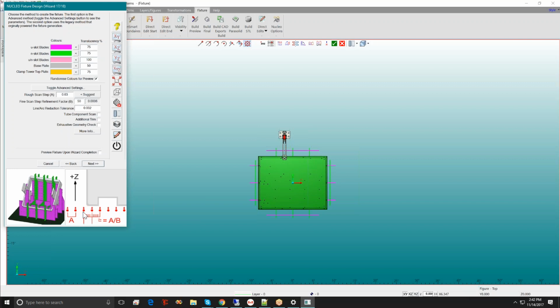And then it goes round, and in the corners, when it thinks it's detected a corner, it goes and looks in that corner at this factor finer. So in this case, it will back up 30 thousandths, and then for the next 60 thousandths, it will look 50 times finer, at 6/10 of a thousandth of an inch in this case. So it's basically a rough scan, then something finer in the corners.